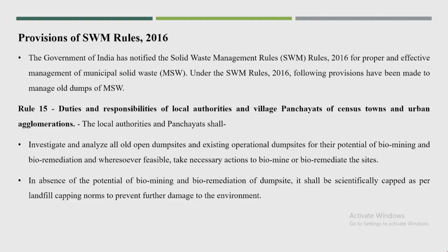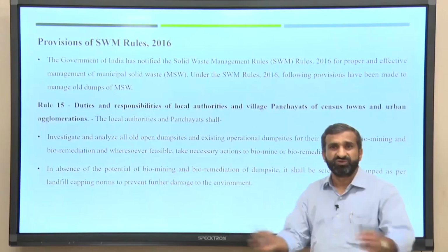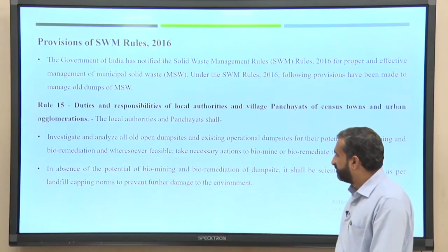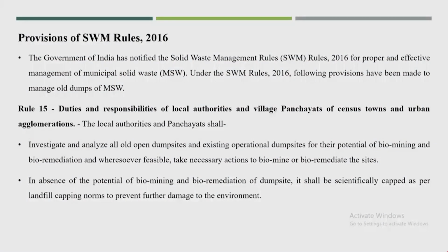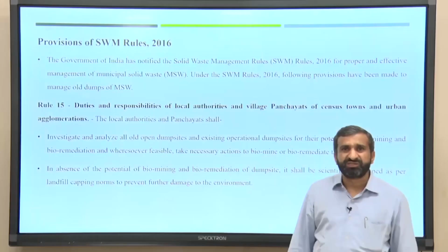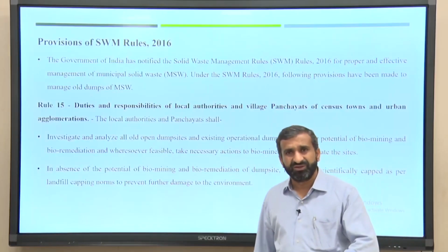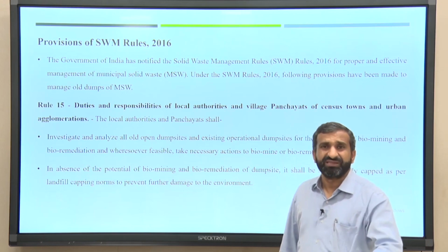In the absence of potential for biomining and bioremediation of a dump site, it shall be scientifically capped as per the landfill capping norms to prevent further damage to the environment. So, it has been explained that if the waste does not have the potential of biomining or bioremediation, we need to have proper scientific capping, not just filling soil on top of the waste material. But I believe that in India, the mixed waste will have a lot of potential where biomining or bioremediation could be possible.